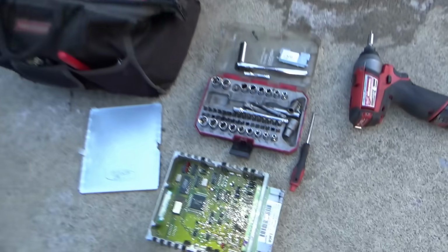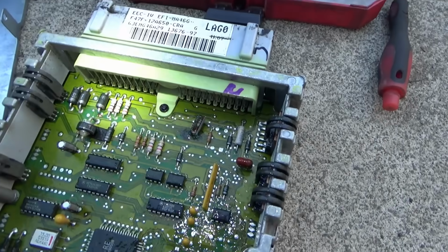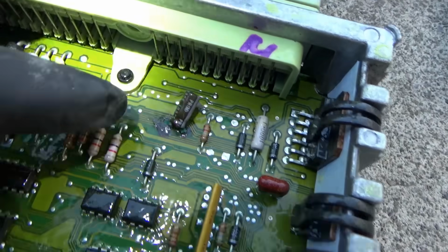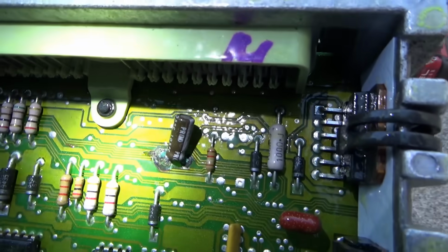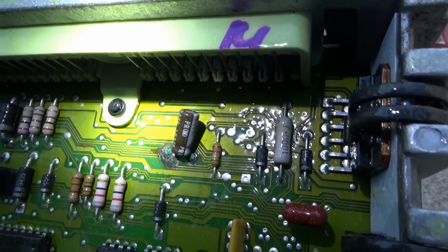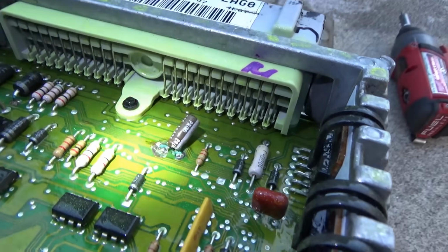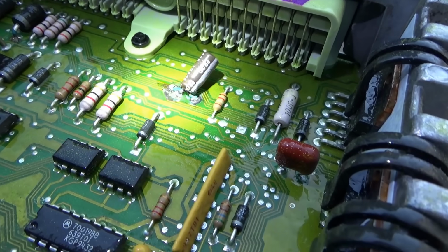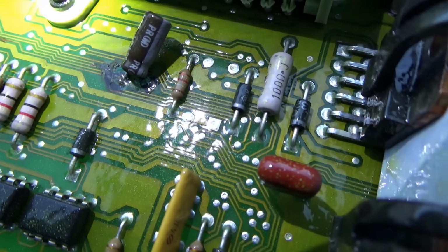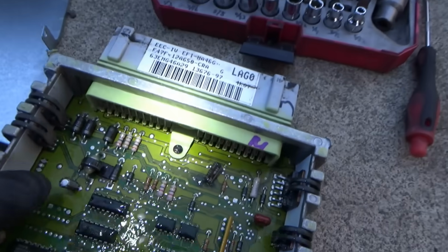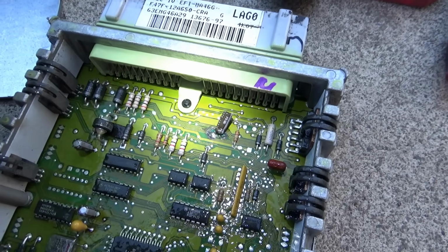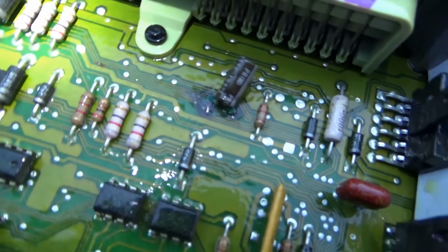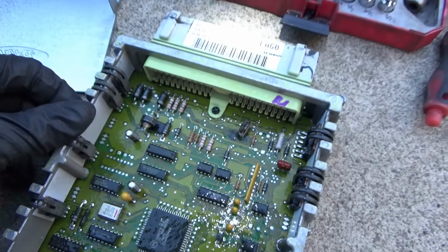Well, it was worth doing a visual inspection. We got a bad capacitor that leaked out and destroyed some traces on the board. So unfortunately, this engine computer is shot. And yeah, there's probably no way to really restore those traces unless you're really good at soldering circuit boards, you know, trace level. But that's it. Boom. Bad engine computer on this 94 Ford Ranger.